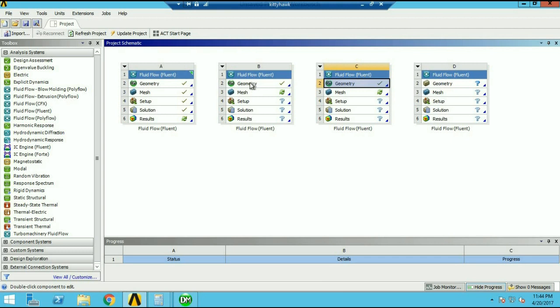I find it faster to, instead of working on the same model and getting the results for each geometry you make, which you could do, just define all the geometries, then mesh each one, and then solve each one. So once we do that for our entire alpha sweep, then we could start getting a drag polar. So I'm going to skip ahead, and in the next video, you'll see all of these completed and solved, and then we'll go on to post-processing and getting that actual drag polar.